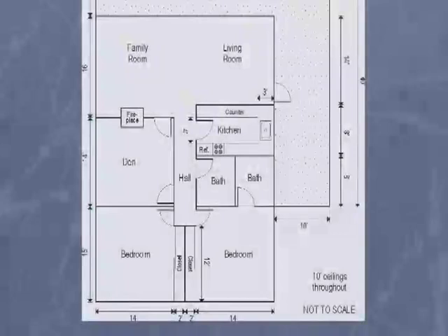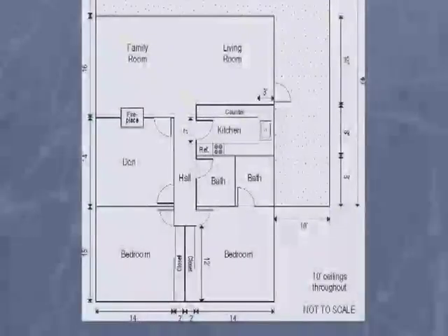Now we have to figure out the dimension of the hallway. If you look at the bottom of the plan, you can see that the two closets are each 2 feet wide. And looking carefully, you can see that the closets are just as wide as the hall. So we know that the hall is 4 feet wide, and we can write that in on our plan, 4 feet. What is the length of the hall? Well, we know that it goes the full length of the den, and the full length of the den, as you can see on the left-hand side of the page, is 14 feet.